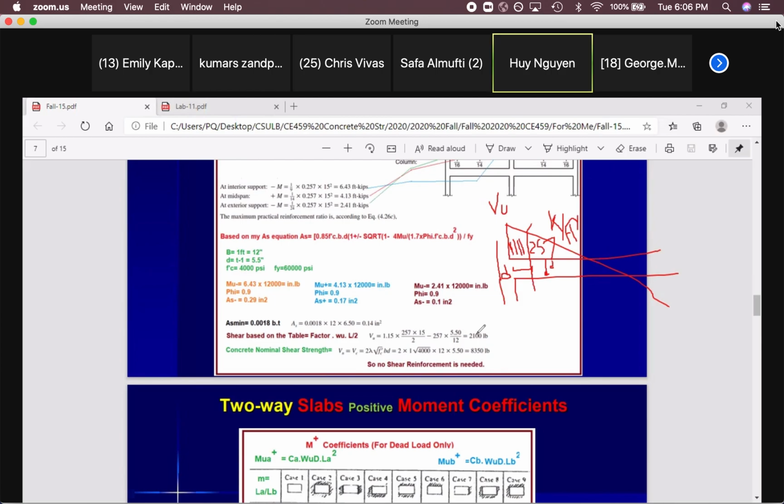I'll have to take a look. Thank you. Yeah, just remember this diagram and work on this, because for sure you need this a lot, not just for a beam, for a slab, for any case. D from face of the support will give us the maximum shear that the element must carry. You calculated VU, but this is bigger than that. You should go and find d from face of the support. That is smaller than that.